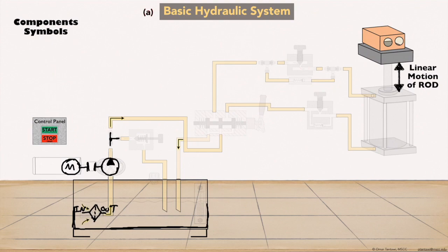There's a T connection. If the oil or the fluid reaches the maximum pressure, then it will go through the relief valve. Most of the pressure valves are indicated by a block, like a relief valve. This is the in. That's the out of the block. A relief valve is a normally closed valve. It has a spring. The spring force is what closes the poppet or the valve, and this spring force can be adjusted by the screw, can be adjusted manually. So it's a normally closed.